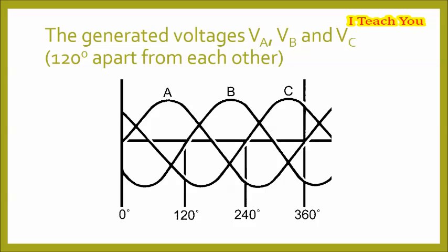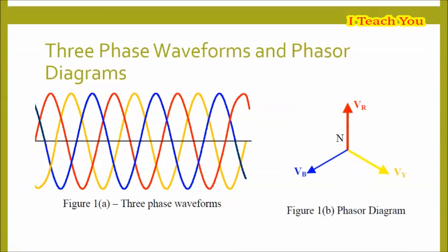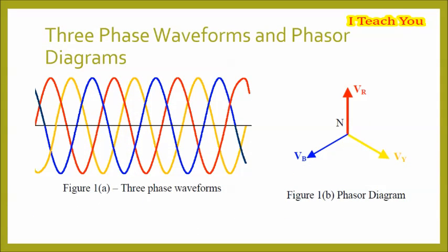As you are aware, to transmit power with single-phase alternating current, we need two wires: live wire and neutral. However, you would have seen that distribution lines usually have only 4 wires. This is because distribution is done using three-phase and the fourth wire is the neutral. How does this help? Since the three phases are usually 120 degrees out of phase, their phasor addition will be 0 if the supply is balanced.